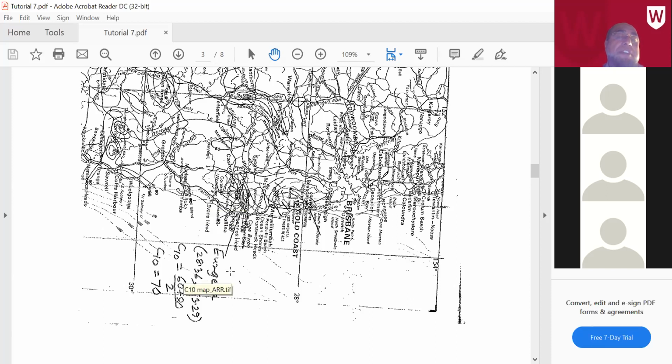And the C10 value has to be estimated from the two nearby control lines. One control line is this, which is 60. You can see this contour is 60. Because our location is here, there are two contours, one contour here and another contour there. One contour is 60, another contour is 80. Our location is between the two contour lines, 60 and 80, kind of in the middle. So you take an average of these two, 60 plus 80 divided by 2. This is a linear interpolation.